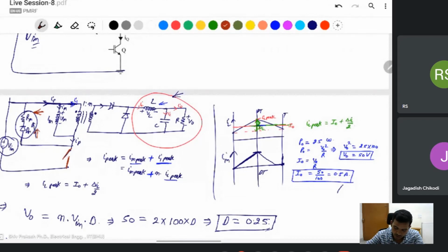Then when the switch is turned off, a spike occurs on the switch voltage VDS, and this voltage is reduced by the resistance given here. The value of resistance depends on the spikes of the VDS voltage, the source to drain voltage of the MOSFET, and the power rating depends on the energy stored in the magnetizing winding.